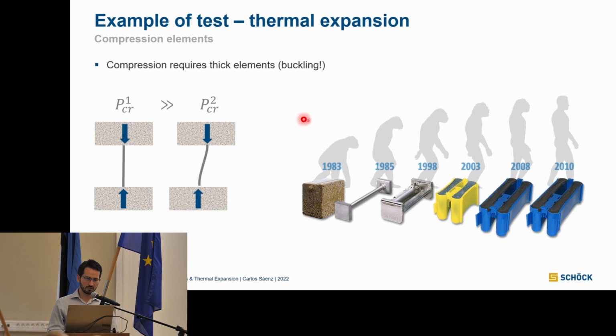If we continue with the elements here, another problem we may have is buckling in our compression elements. You get to see this tray element. It will withstand more force than this one, of course, because we have the axis already moved to where the force is applied. So here it is better at withstanding the force because it's not deformed.